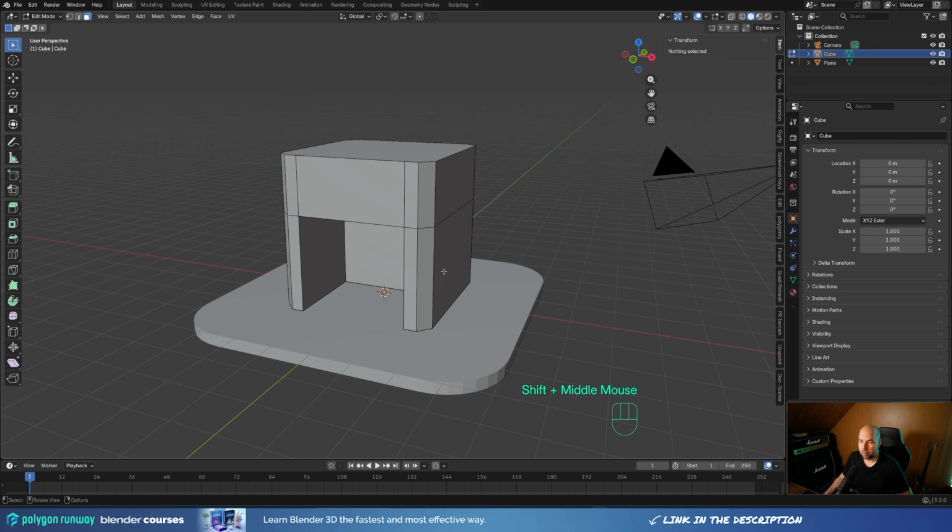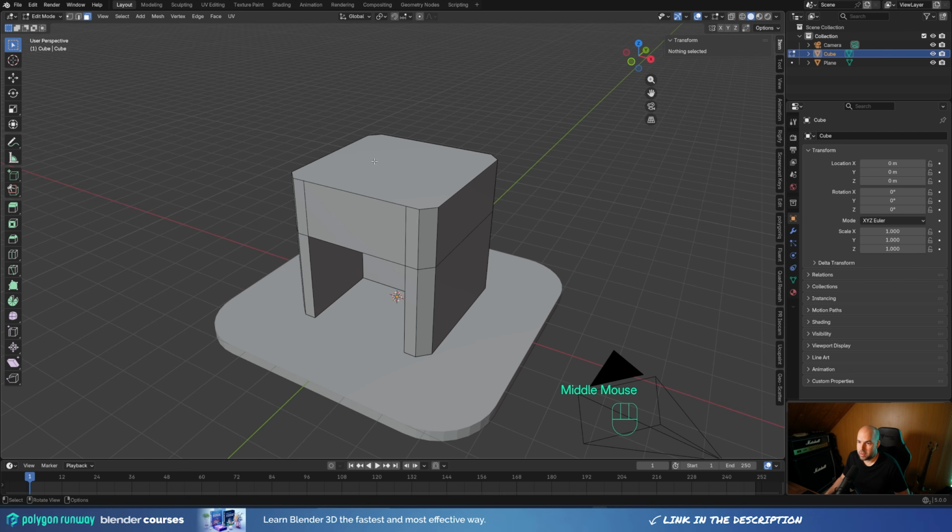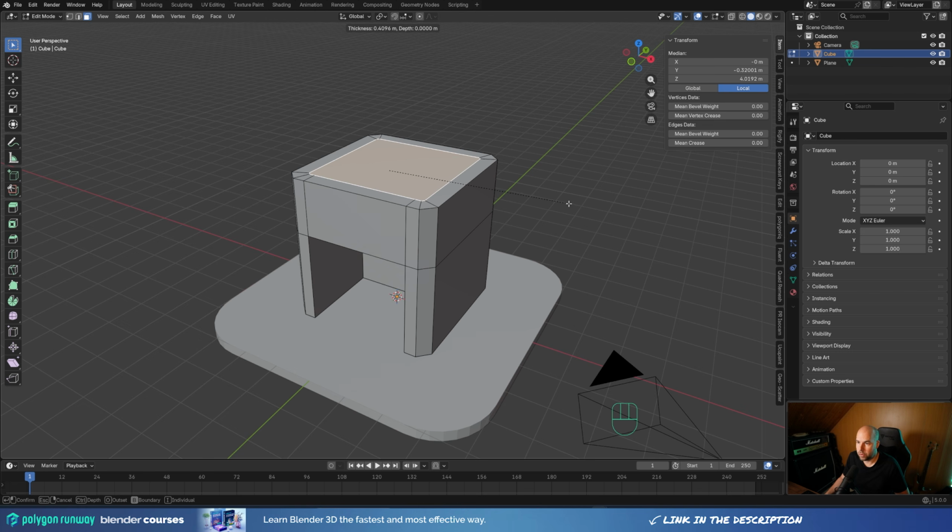And now let's block out some other geometry. And this is what I generally like to do when I'm creating a scene. I like to create really basic primitives, basic objects, and basically just block out the scene to see how it looks. And then later I go in and add modifiers and add different details. So let's rotate this a little bit and select the top face here and press I to inset and do an inset like this. Be careful to not go so deep as to, you know, touch these vertices on the inside. And now press E to extrude this down like this.